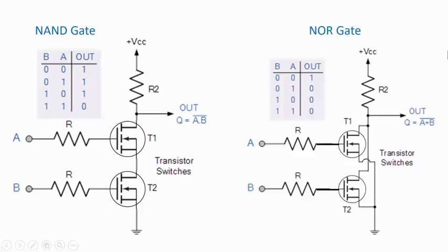And how do you make the NOR gate? Similarly, you just need to put the two transistors in parallel. So you connect to the join of these two. The sources of these two transistors are connected common and path to the ground. And again, a resistor is put here, and the output is taken across here. And the output will be NOT OR, right? You have to make the NOT OR.